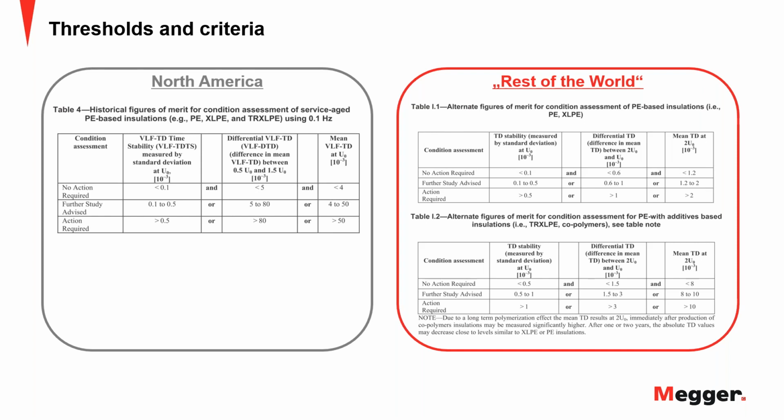But if you remember the chart that Robert showed you, when he showed you the depiction of the wave shape, on the cosine rectangular you have the 60 or 50 hertz transition, and then you have a 5-second plateau phase. And that's how the leakage current can be measured, or why the leakage current can be measured on the cosine rectangular. At the end of the 5-second plateau phase, we can measure the leakage current. That's a very fundamental difference between the two wave shapes.